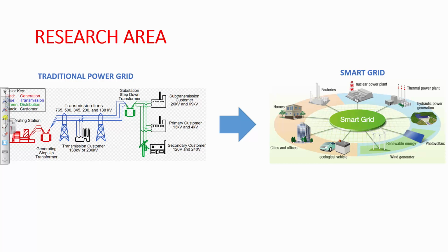Here, you don't need a transmission line because you are generating that megawatt close to the load, so you directly supply that power to the customer. That technique is called distributed generation. That means it's a generation unit built or installed at the distribution level, here instead of there. So you don't really need a transmission line to transmit that power.